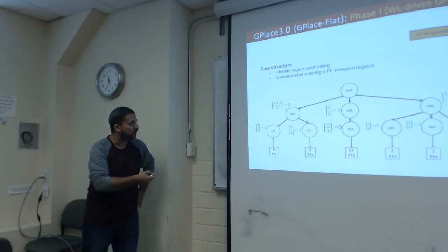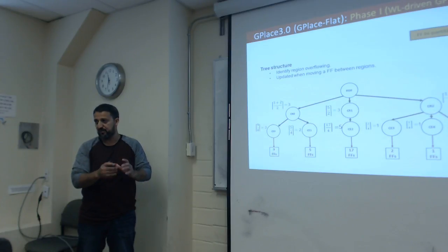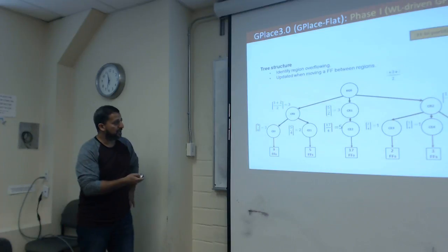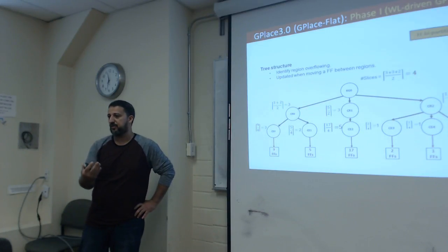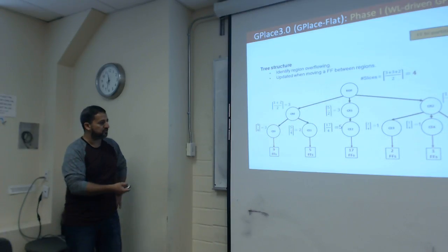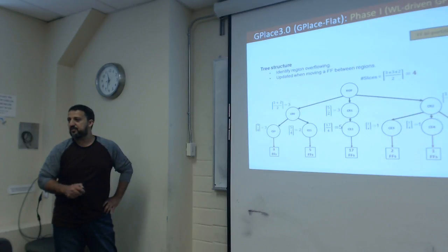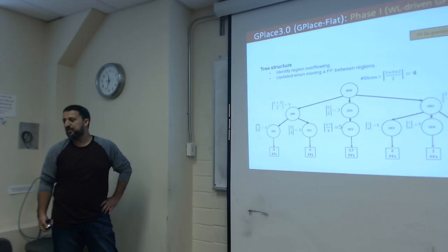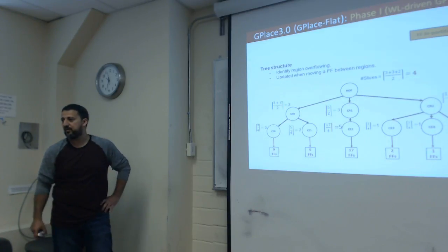This is the number of groups or half slices required. Now we add them together and divide by 2, so we end up with the exact number of slices required. If we ignore the control signals, we have 37 divided by 16, so up to 3 slices is enough to accommodate those, correct? But actually, to have a legal solution, we need 4 slices.